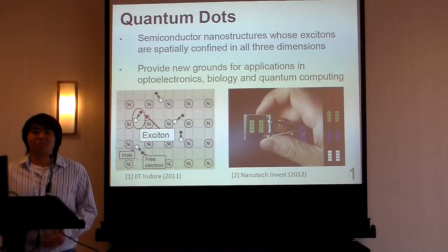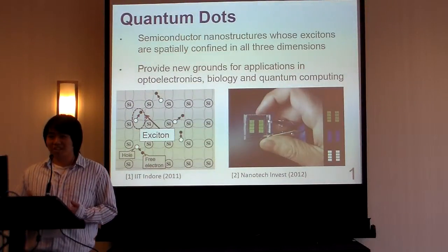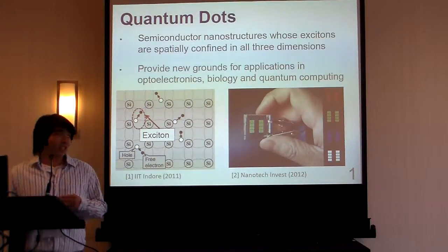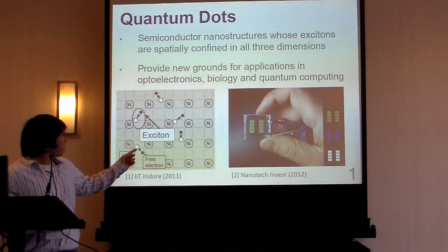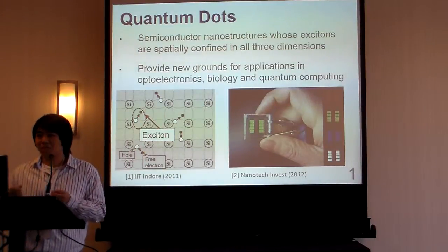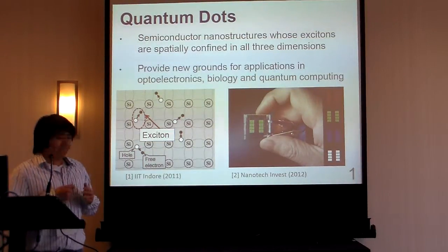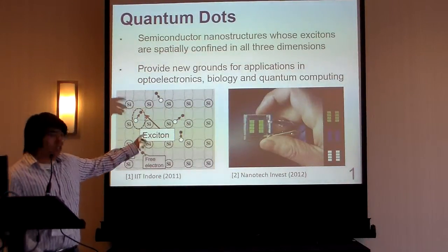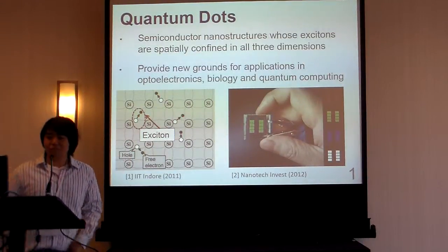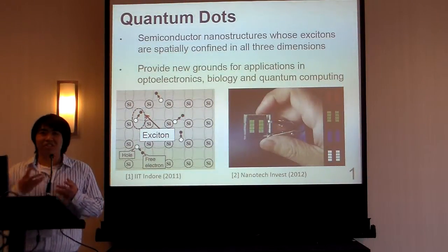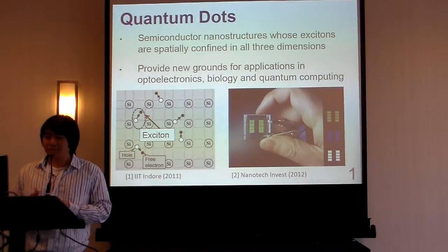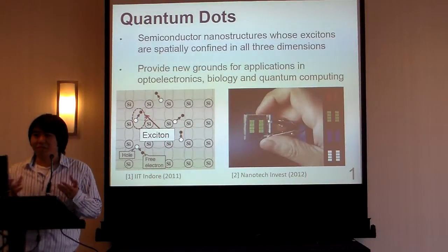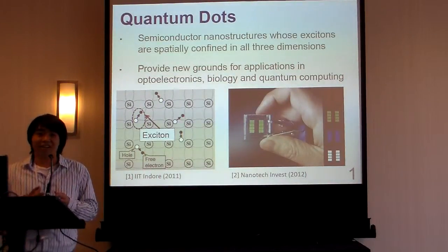So semiconductors are materials with electroconductivity that's intermediate between insulators and conductors. When semiconductors conduct electricity, electrons separate from atoms, leaving behind holes. After an electron separates from an atom, leaving a hole, this electron-hole pair we could call an exciton. Quantum dots are basically granular semiconductor nanostructures, and in quantum dots, these electrons are not free to move around everywhere, instead they are spatially confined.